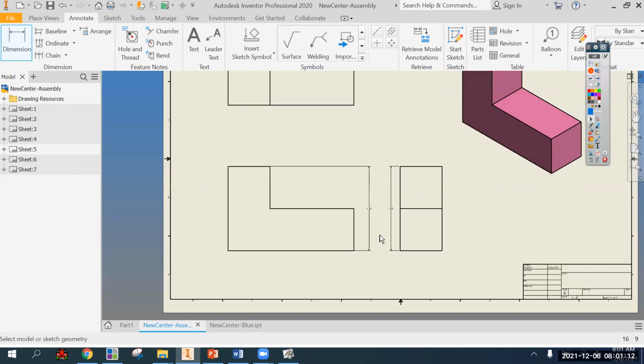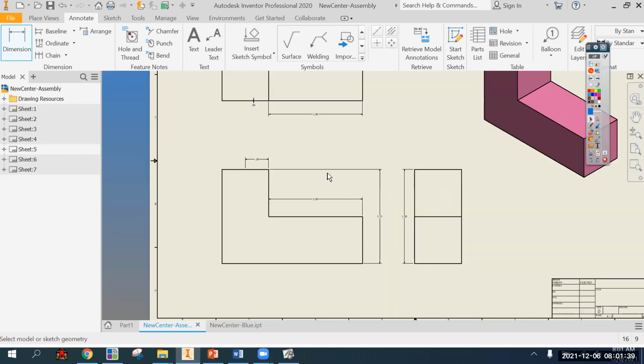It's not a huge critical error, in that if you had both of those dimensions on there, somebody would be confused and it wouldn't work. They wouldn't understand how to make it. But if you start having everything on there twice, and these aren't even very complex designs, it would start to get a little crowded.